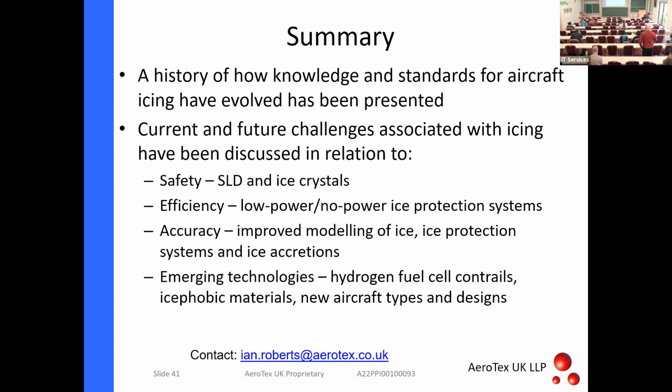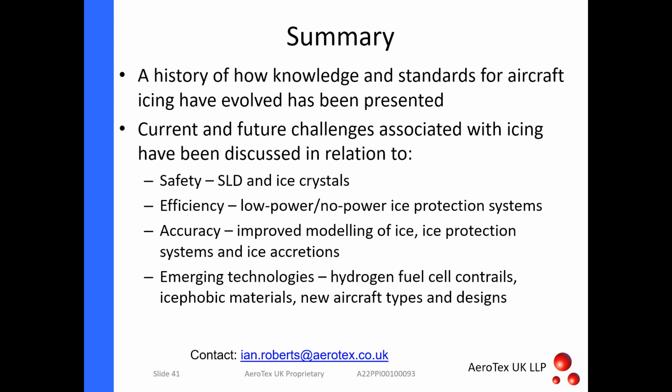Thank you. In terms of the erosion, we get issues for the ice crystals. You end up with quite pointy ice accretions because the crystals are actually eroding. Some of the crystals are forming the ice formation, but these ice formations are also getting eroded away by the crystals themselves. So they're changing the way in which the ice forms.